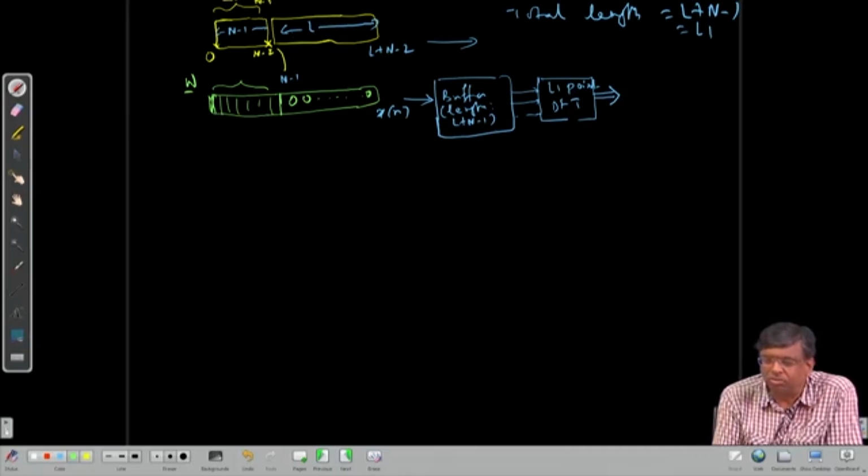That is, if I carry out circular convolution between this, that is filter coefficients as it is 0 to n minus 1, not n minus 2, n minus 1, and remaining L minus 1 points actually now, they are zeros, and then we carry out circular convolution between these two blocks, that is DFT here and DFT here, multiply, inverse DFT, which in time domain is circular convolution. Then first n minus 2 results are incorrect, from here onwards results are correct, and that is what I want, because my point of interest is from here to here.